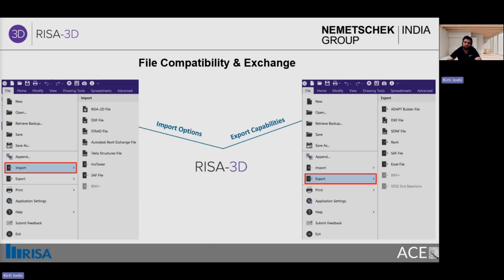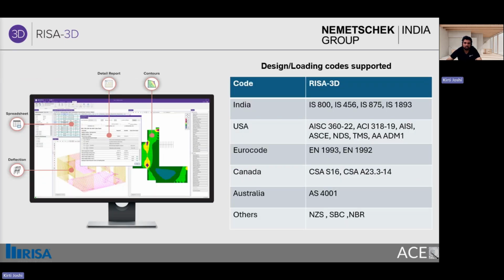Basically, it is an open file format to exchange data that contains all of your member information, section geometry, and the forces. Some software, like IDEA StatiCa, supports the SAF file, so if you want to integrate this with IDEA StatiCa for the connection design, you can.